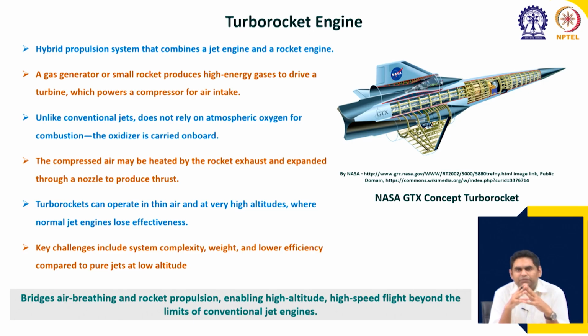An air breathing engine has much higher efficiency as compared to rockets, because rockets need to carry their own oxidizers. So, their thrust to weight ratio is very poor as compared to a jet engine, for the same speeds of course. When the jet engine cannot be used, when the air density becomes too low, like near space or in space application, the rocket engine will take over.